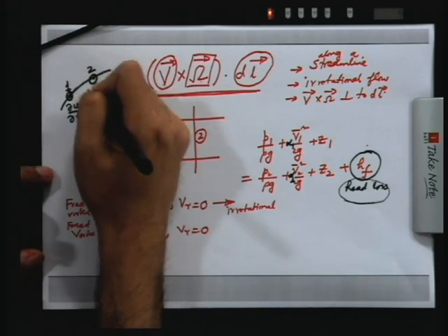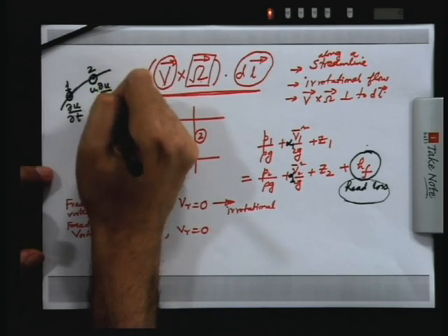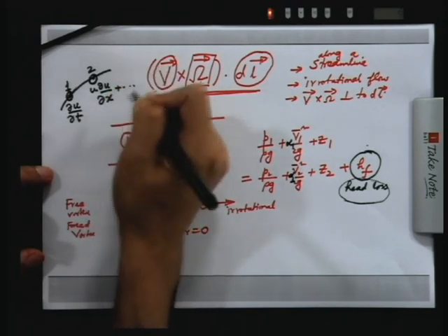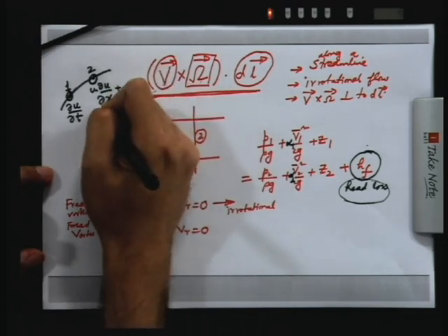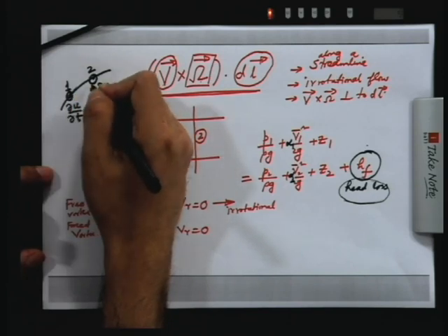So, there is a component of acceleration, I am just writing one term, u del u del x. I am not writing the other terms. This is because of advection of the particle. With time the particle has come to a new location, at the new location it finds a different flow field, and therefore there is a change in velocity of the particle.